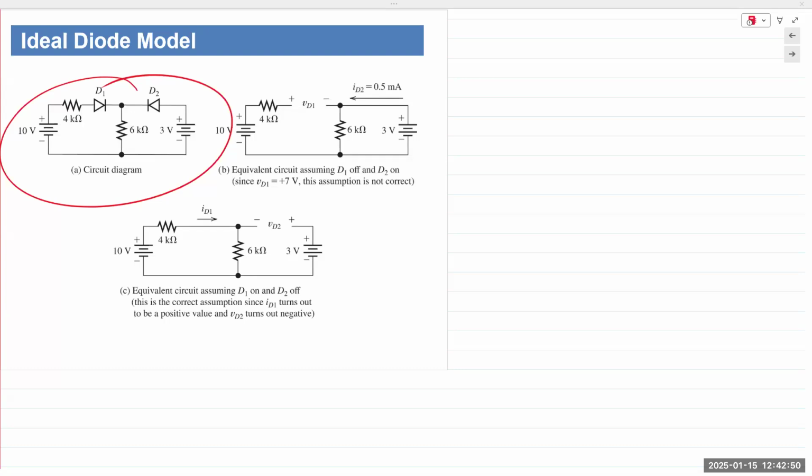And then how is a diode turned on or off? Is it just by flipping the direction? Well, it's not really turned on or off. It's basically what is given to us in the problem. In a real life circuit, of course, if you wanted to turn a diode on or off, you would simply take a look at the voltages at the anode and cathode. Increase the voltage of the anode with respect to the cathode, and it's now on. If it's the opposite, then it's off.